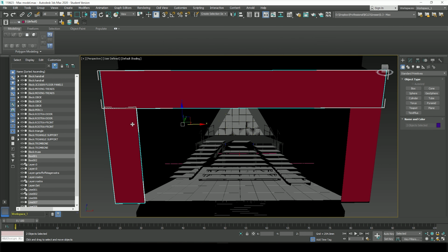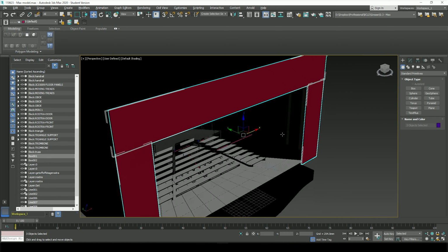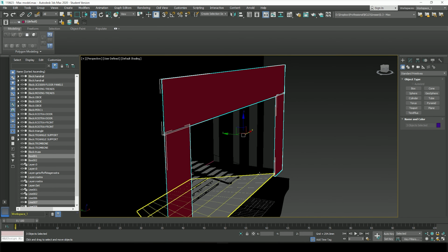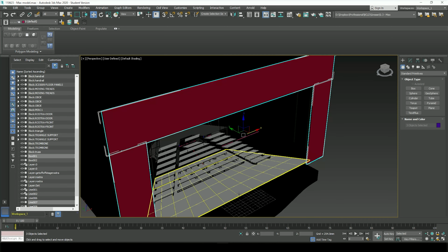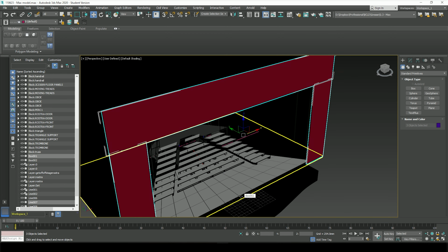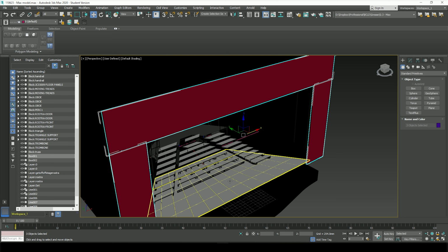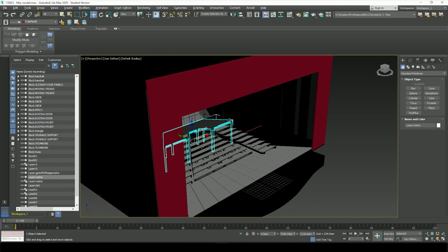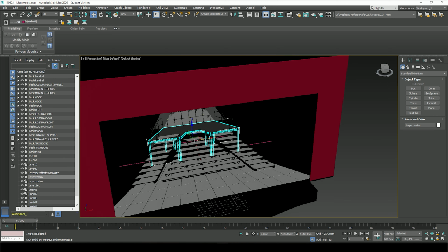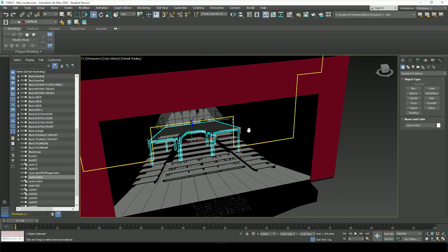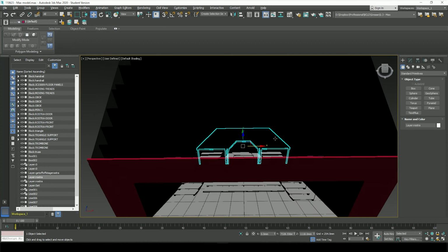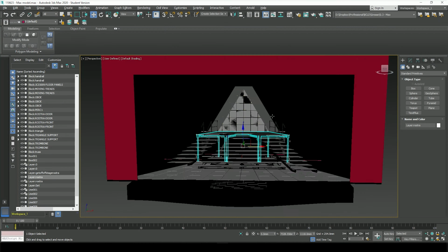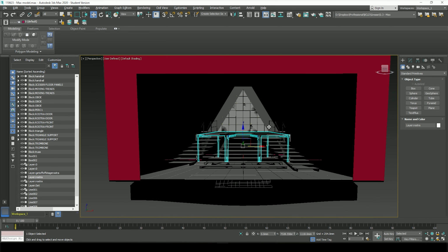So if I selected this proscenium, for instance, and made that an FBX, that point there, what it sees as the middle of these three objects, will always get put down here to the center of your scene. Same thing, if I selected this rostra at the back here, that's now the origin, it will position it here. So basically every time you import an object into Wysiwyg, you'll lose its position on stage, which is really frustrating actually. It's something I don't like, and I've reported it, but apparently other people like it, so it's just me.